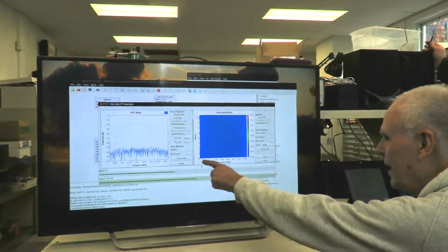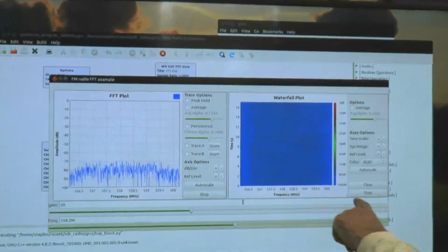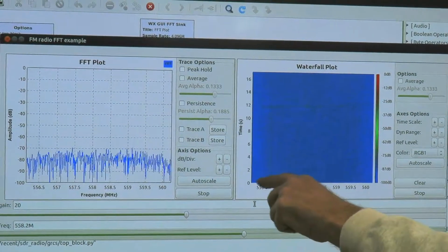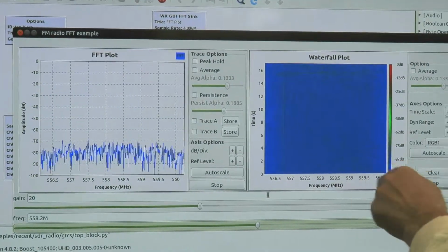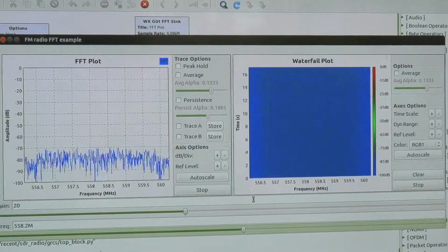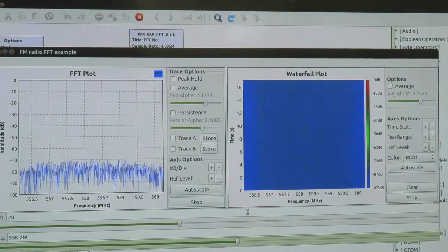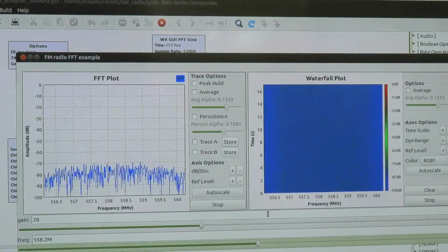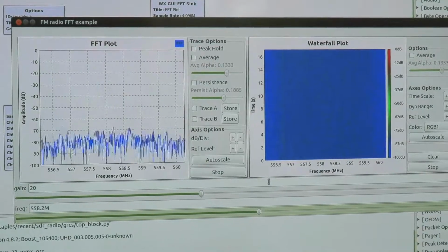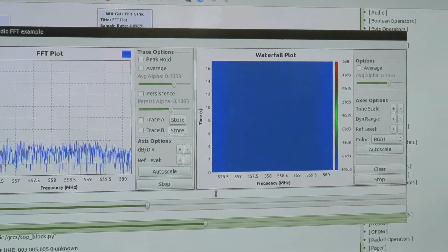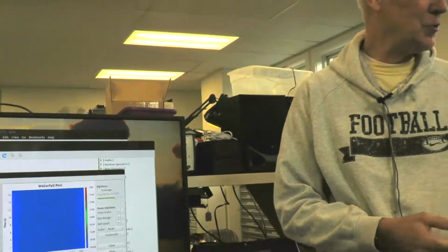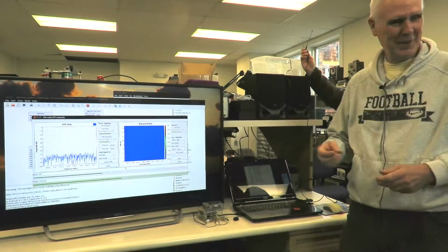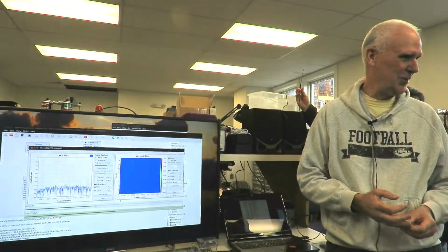The HD TV signal is about several megahertz wide, so the signal should look kind of like this. You should see that this pilot signal is about 300 and some kilohertz off the bottom end of the channel. So that's an HD TV signal. All it is is noise with a pilot in it. But so there you are. That's the demonstration, and what you're looking at is a $20, very decent, and with a better antenna, very decent spectrum analyzer that goes up to.